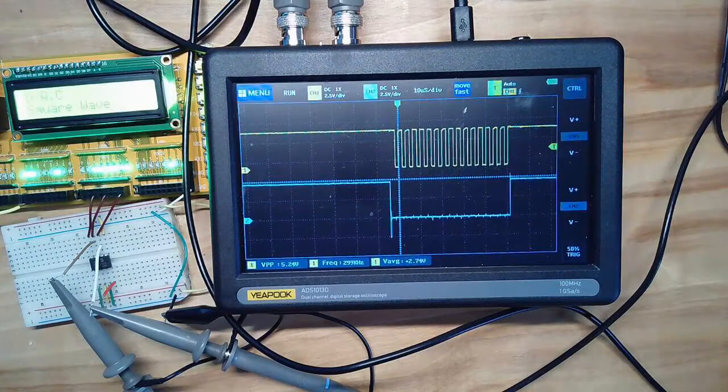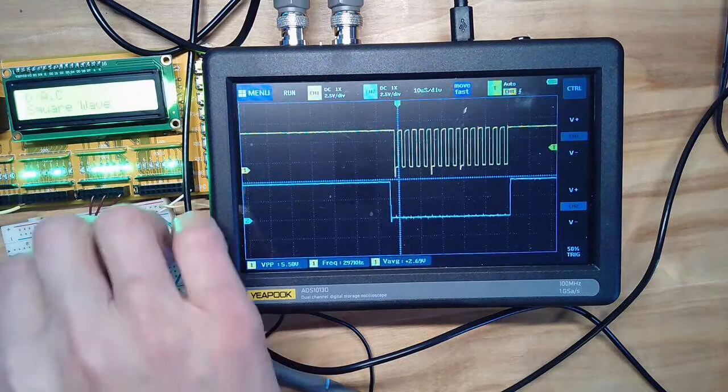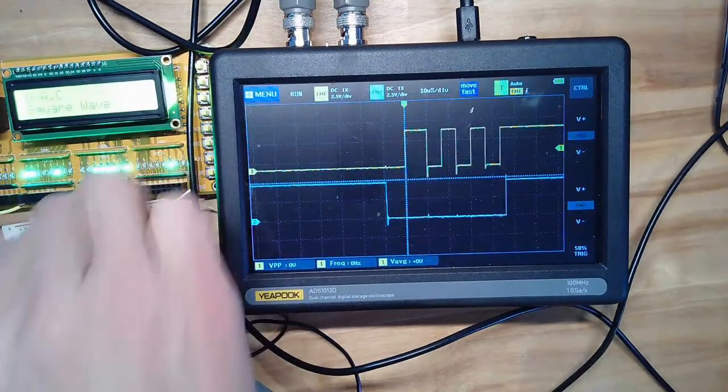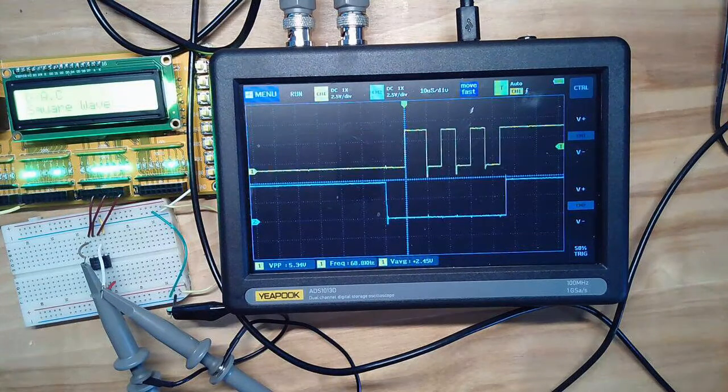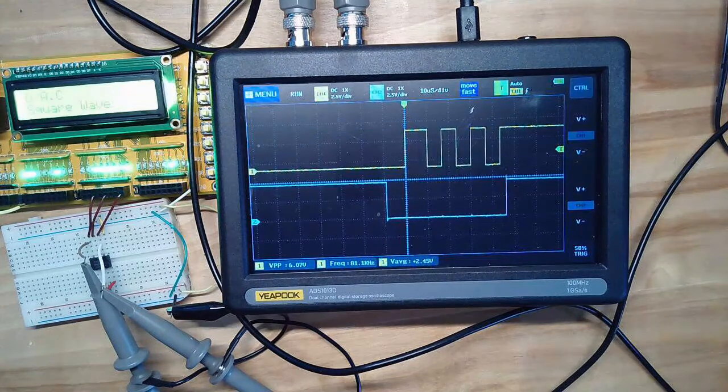So to illustrate that, this is a program I'm going to look at in just a sec. This outputs a square wave. I've got my 3 data lines, RC0, RC3, RC5, going to chip select, clock, and data. The blue line here is your chip select. When it goes low, there's my message, end of message, and that's my clock line. I send 16 clock pulses. If I move this over one, that's my data. I'm sending data to output 2 different voltages, which is what you're seeing there.